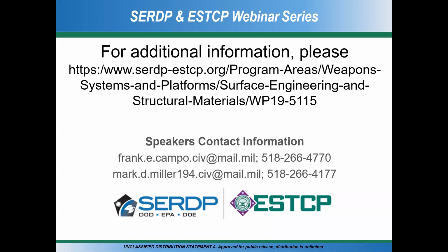Excellent. This is a question from Lockheed Martin. Do you need to treat the water for the waterjet process using reverse osmosis? Will you need a chiller system? And what is the cost to set up and run a line? I can briefly talk about that. Depending on your water quality, where you're getting it from, you have to do an analysis, and obviously the critical parts are nozzle buildup and pump life, because you're creating pressure by either reciprocation or another type of intensifier.